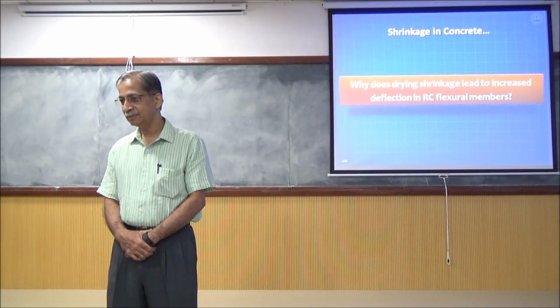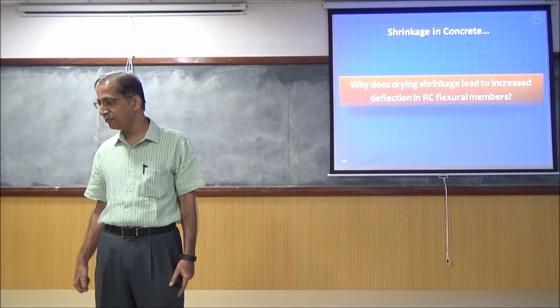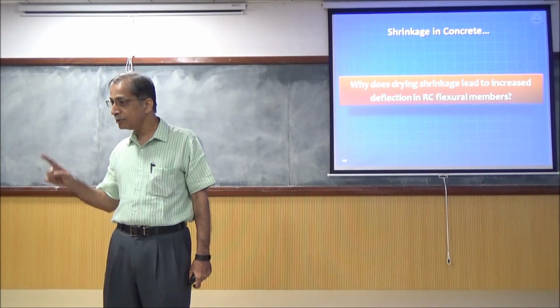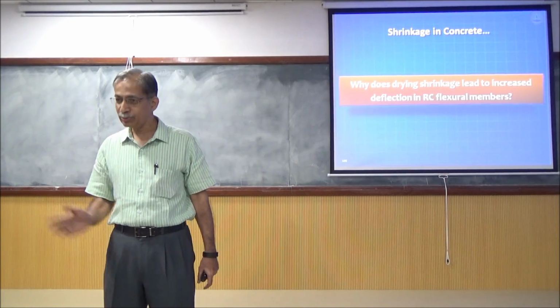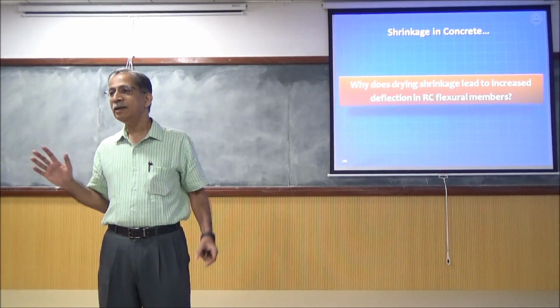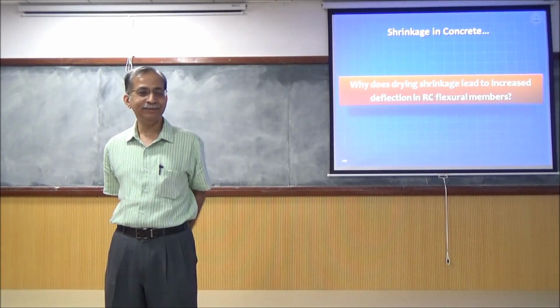Due to shrinkage. Drying shrinkage. Yes, says the code, because the code wants you to check for long-term deflection. You will also get an increase in deflection due to creep, because you have sustained load. But due to shrinkage, now a simple question: let it shrink, why should it deflect?